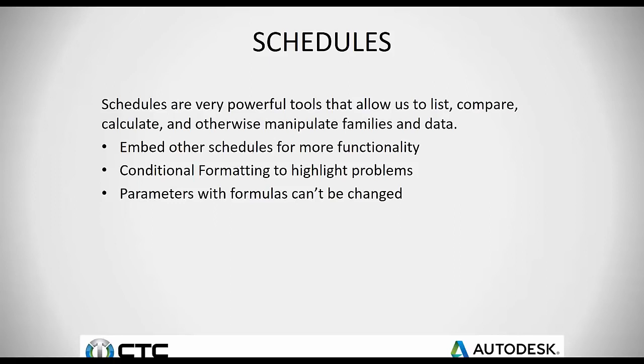So schedules are really powerful because we can actually pull data out of our families and we can run calculations. We can embed additional schedules for more functionality. We can throw in some conditional formatting that is going to highlight problems or anything else that we want to show. Parameters with formulas within our families: if we're applying a formula in our family, those formulas cannot be changed within the project. You would have to edit your family in order to do that.